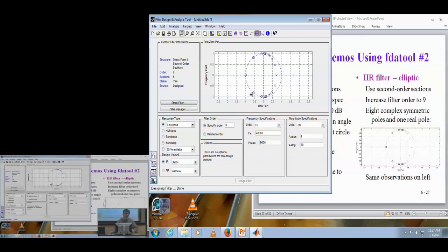Same with the zeros. Now, manually, I can use repeated roots, and I do. If I design a filter by placing poles and zeros manually, sure, I can put a repeated root, and we do this in practice. Have you ever seen an even ordered system that had 2 real valued roots? Off these filter design algorithms, I have not seen it, but again, manual placement, yes, absolutely. And we did this when we looked at biquads, bandpass filters and band stop. So we did a band stop filter where both zeros were